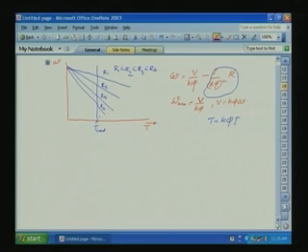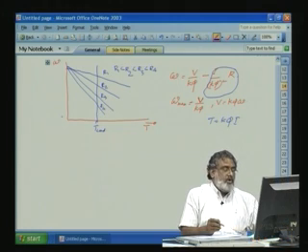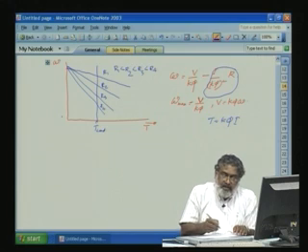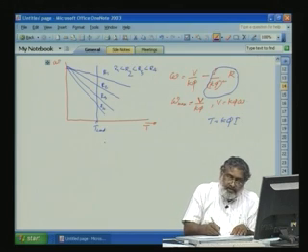We want in a system, especially in modern electric drive, it is frequently necessary to stop the drive or quickly accelerate or reverse it. So, the torque speed characteristic should be not only in this quadrant, it should be in all 4 quadrants. That means, we have talked about the 4 quadrant operation.